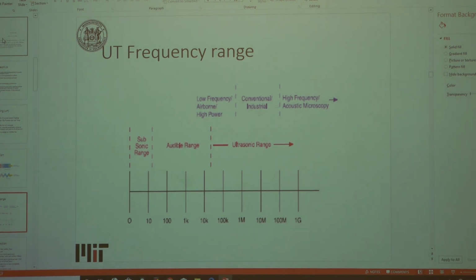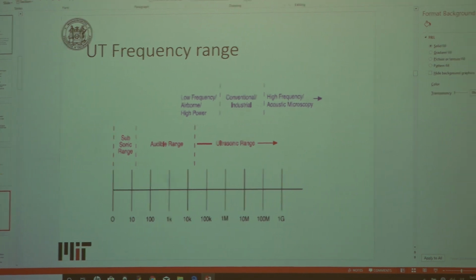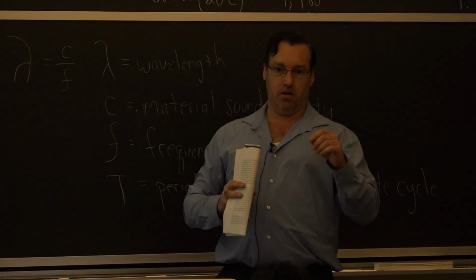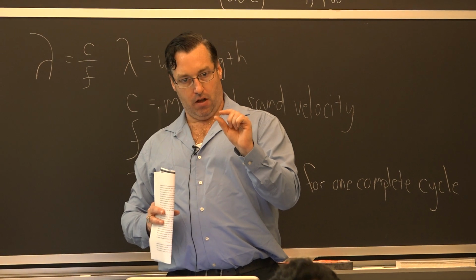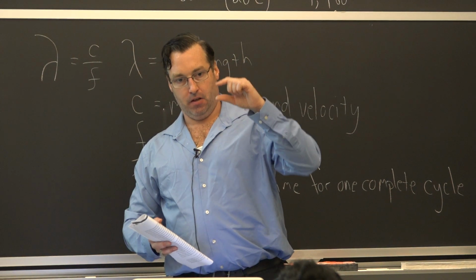So you have what's called A scan, B scan, and C scan. The A scan is simply the amplitude versus time. All right, it's like the sine wave. The B scan is when you add in another variable, so it would be with thickness. And then the C scan is if you want to actually image it, and that is when you can try to size the flaw or locate the depth.